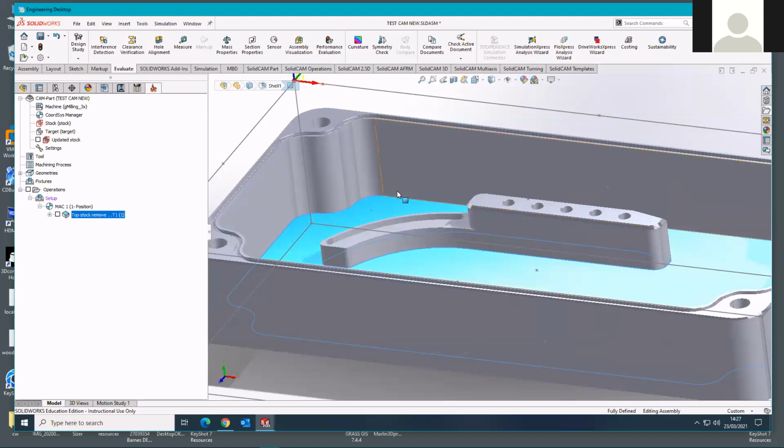So we'll pick a tool that has teeth which are as tall as the entire pocket, so that we finish it in one single pass that runs round the inside. And that way we'll get a nice, accurate, visually nice finish on the internal face of the box there, rather than getting slight little discrepancies and witness lines between the various levels.